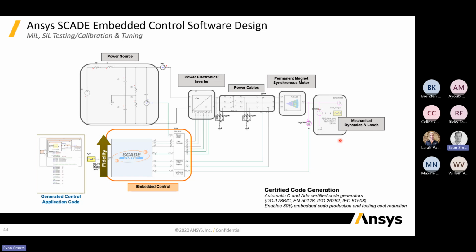And then we've connected that to the control software. Okay, so the embedded control software through our components. We have our input, which is maybe our driver's inputs into the controls, and we can see how that then controls the rest of the system. So we can test this model under different input signals and see if the control software actually behaves as intended. Does it control the motor as we expect? Or does something happen that is actually unsafe, and then we need to go and correct that?